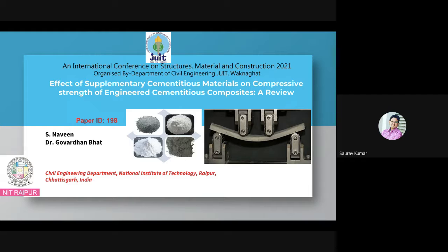Actually, ECC is produced with microsilica sand, which is a costly product, so it makes ECC more expensive to produce. So we are completely replacing that silica sand with our regular river sand, which is available, and studying how the behavior differs in compression, in tension, and in durability.